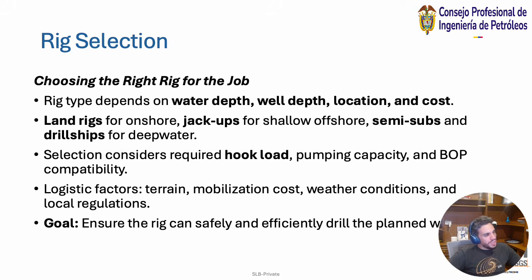So once you've selected which rig or which depth or whatever, you need to also take into consideration things like the hook load, the pumping capacity, and the BOP compatibility, right? So at this point in time, we are talking about depth and we are talking about pressure.